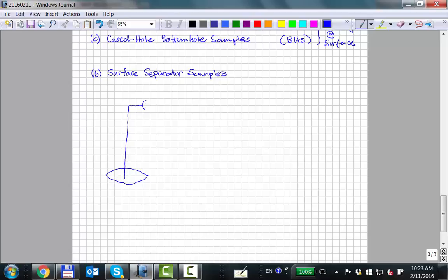And then we're going to have a single separation piece of equipment, a single surface separator. It's going to be what we call a test separator, typically. It's for a single well. Big separators will often be for 5 wells or the entire field. Okay, those are production separators, much bigger and a lot more equipment.